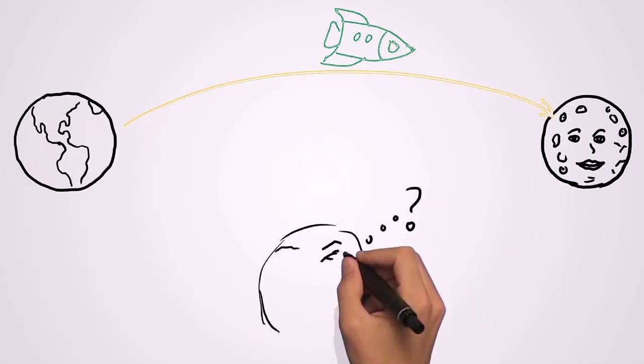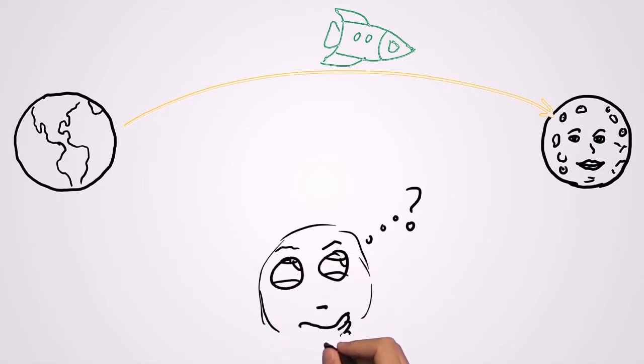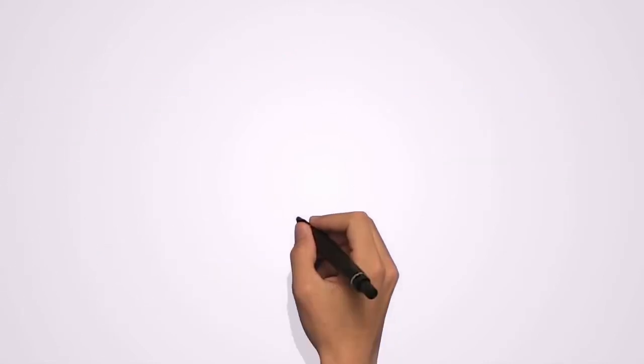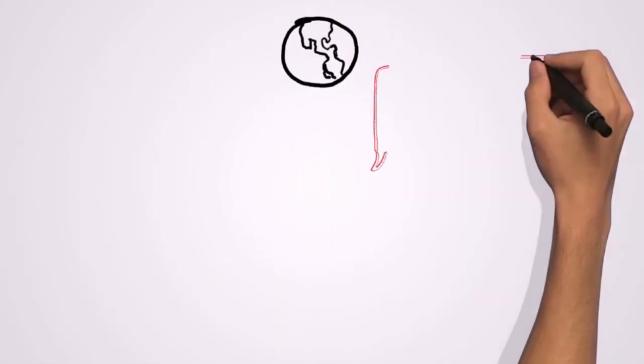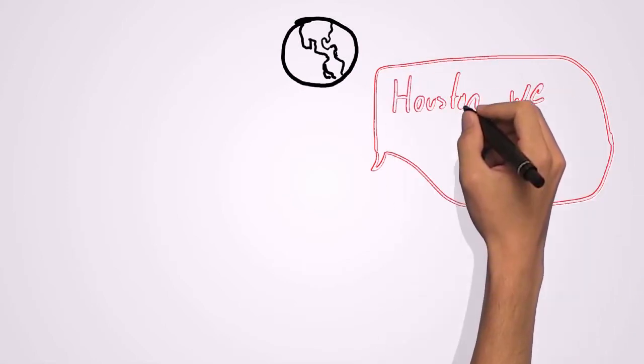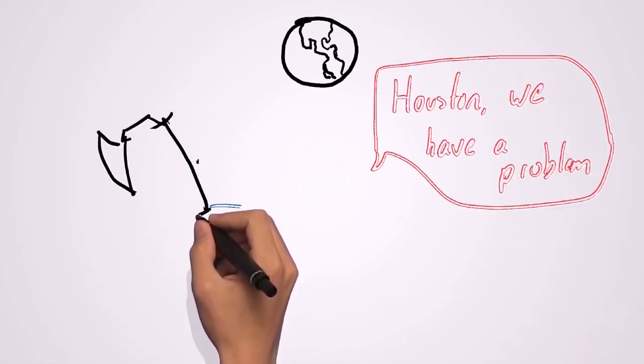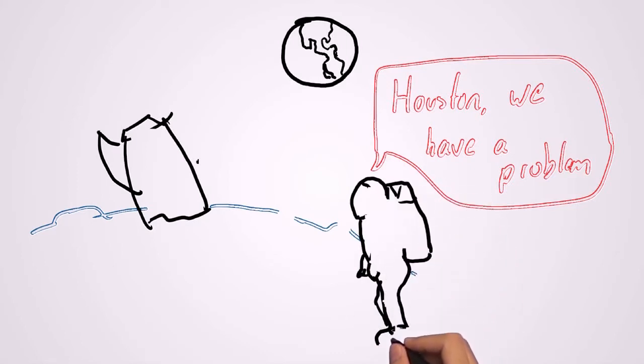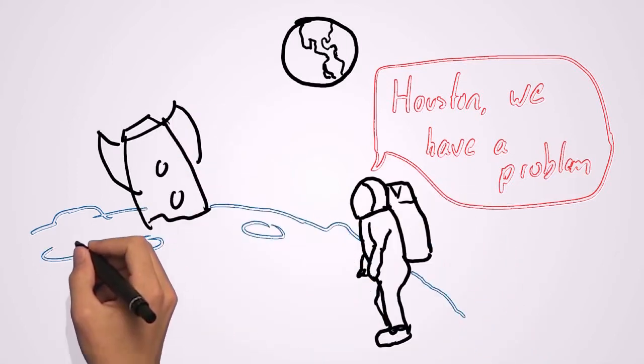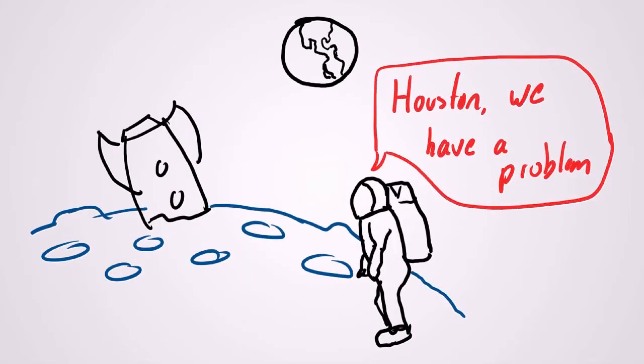In addition, you can also use sensors to measure your position. However, this measurement will not be perfect because every sensor is subject to noisy conditions. Then, what is the best way to know your position and velocity? Here is where the Kalman filter comes into play, as it fuses information from the model and the noisy measurements to provide an optimal position and velocity estimation.